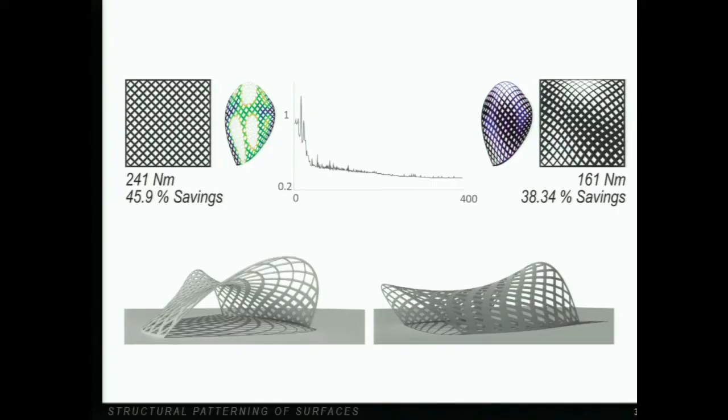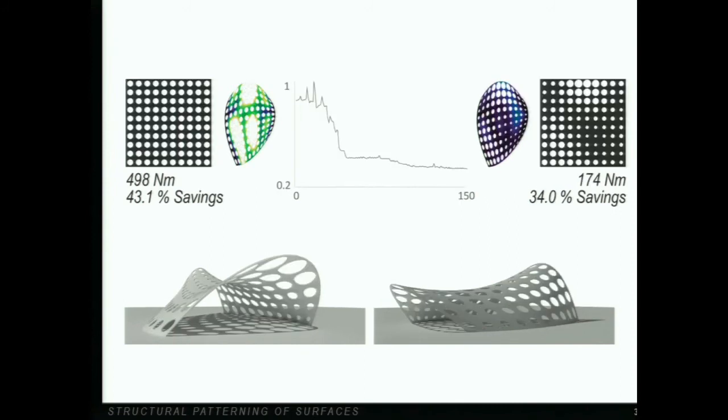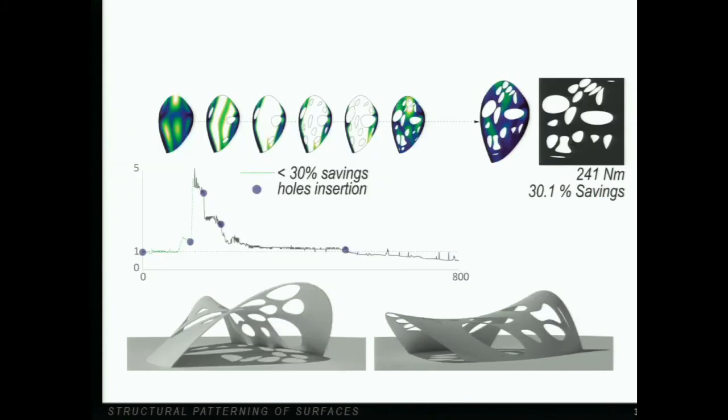Similarly to the prismatic beam, we use the fixed top workflow to design a structural pattern on the shell with distortion and scaling. The structural pattern, as before, saves material while increasing the stiffness of the structure by redistributing loads. And of course, with this method, we're free to explore any whimsical pattern we'd like, which is really what lies at the core of the method: we're able to integrate the design intent into what was initially an optimization problem.